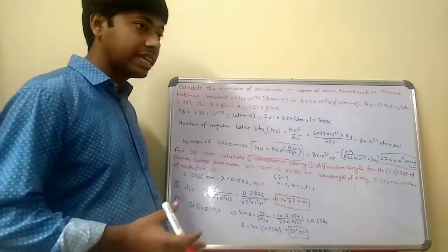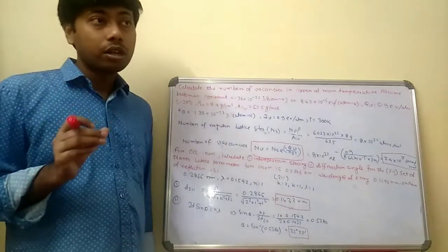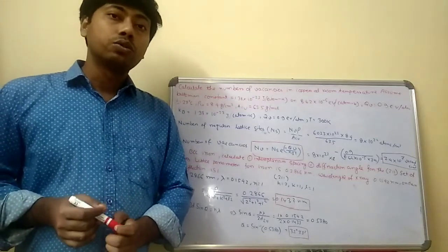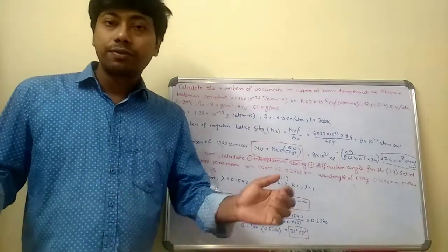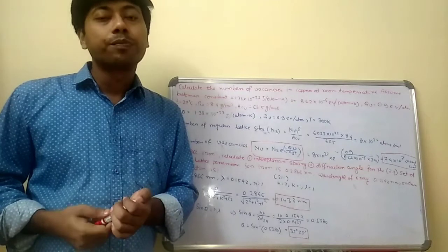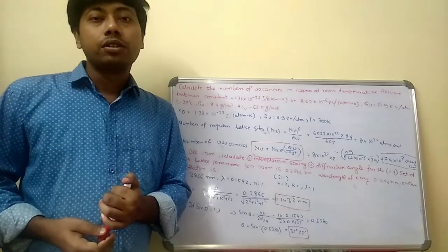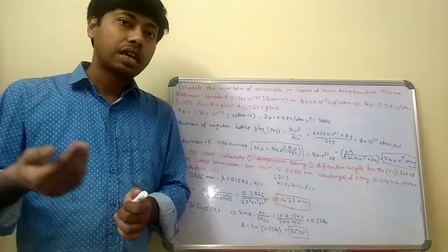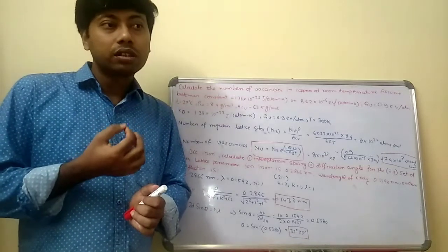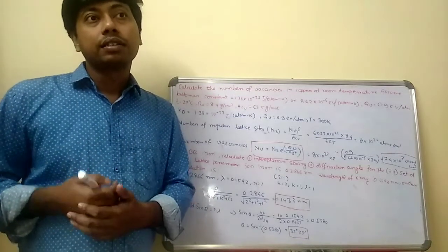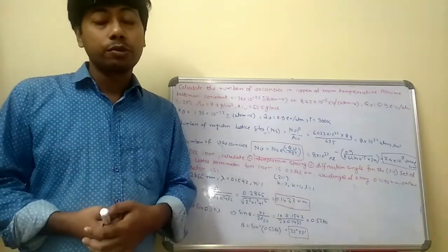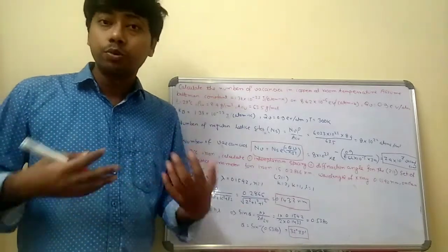So these are the number of vacancies that can generate, but this type of vacancy is very important in particular materials, because crystal defects are generally used to improve the properties. As you know, deformation is the reason there are dislocations. Deformation is the main thing in a material when you apply load, but in the inner part of the material you can see that some dislocations occur, and due to dislocation movement, the deformation occurs. So dislocation is also one type of defect. Similarly, the vacancy is very important, because it improves the mechanical properties.